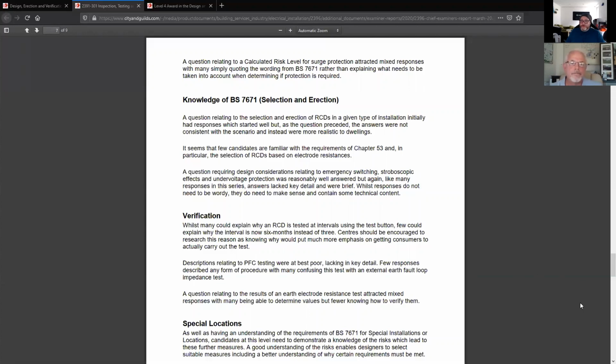Why isn't it adopted? Why isn't what adopted? Testing short circuit current at the end of circuits? I don't know, we've been banging on about it for years. Same as testing neutrals. Why don't we test continuity of neutrals? We need to ask the people who write the book.